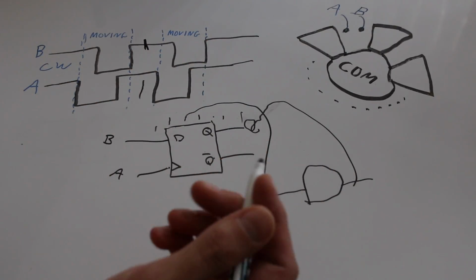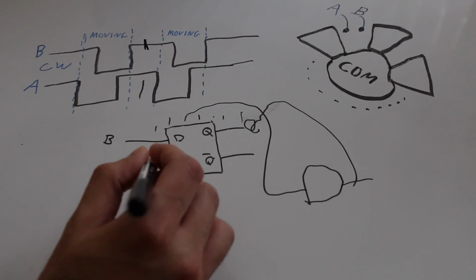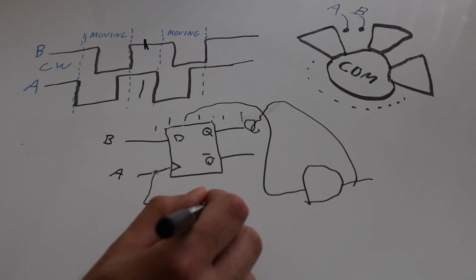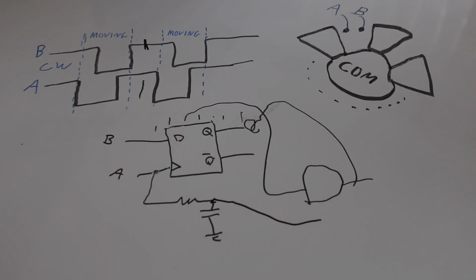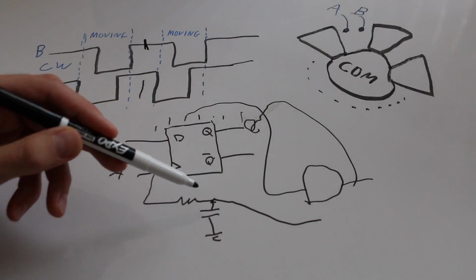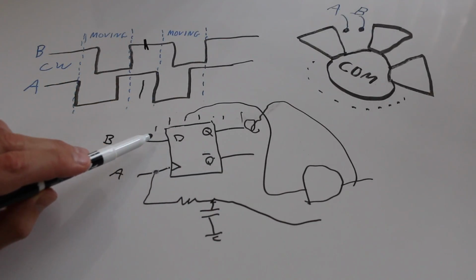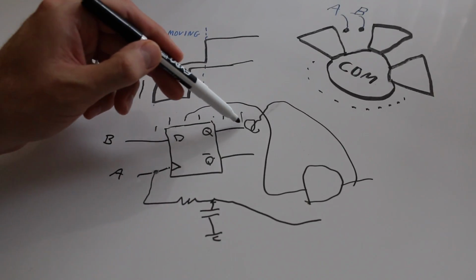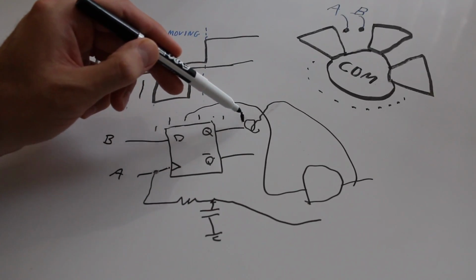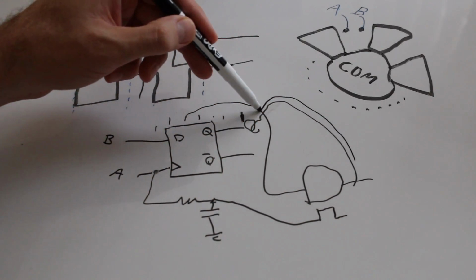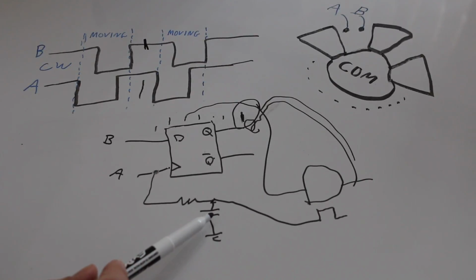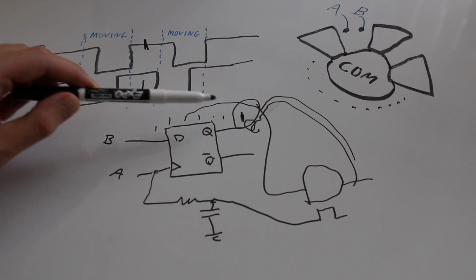So you could try to do things like maybe take your clock and do sort of a time delay with a capacitor, resistor, filter. And then this is a delayed clock, so you can figure out how long it takes for data to propagate to Q. By the time this is stabilized at your most accurate current data, sometime after that, you generate your clock and your circuit can then look and see the valid 1. But this depends heavily on accuracy of this timing circuit, which can change component to component or change over temperature. Too much hassle with this, I think.